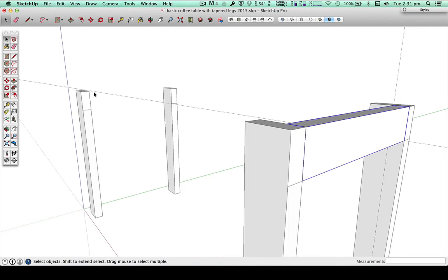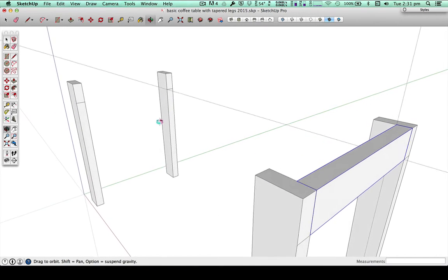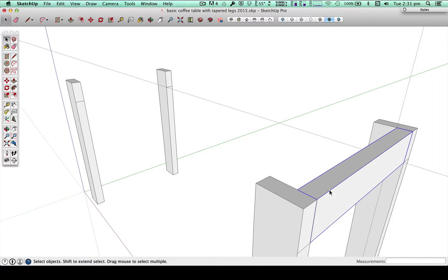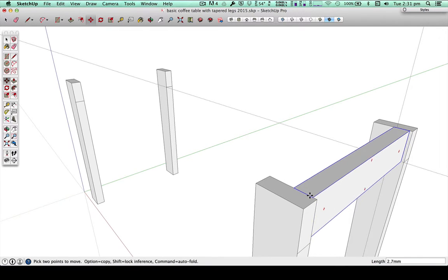Why not just put this object down there? I'll just rotate our view a bit so it's a bit easier to see. But it's a no-brainer that this piece of timber here, this point here, has to go to that point there. So if I just hit the M tool, and I'll deselect to make sure it's easy to understand, hit the M tool, as I roll over it, it automatically selects it. I want to select that part there, from that endpoint.